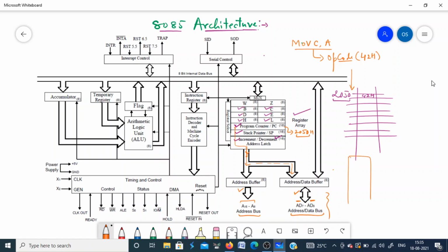So you have an 8085 processor. You have 16 lines which carry the address as well as the data. The higher 8 bits, that is A8 to A15, are used for address only, which means they will be permanently connected to the decoder that we are using for memory address decoding.